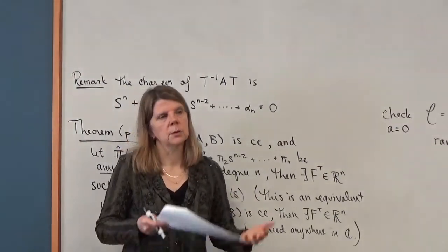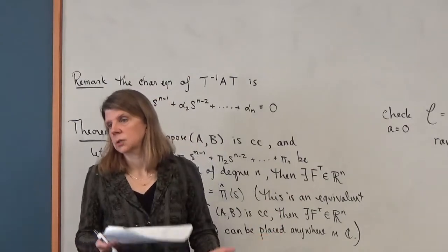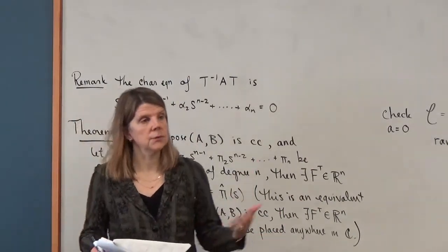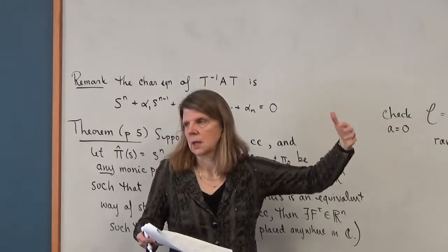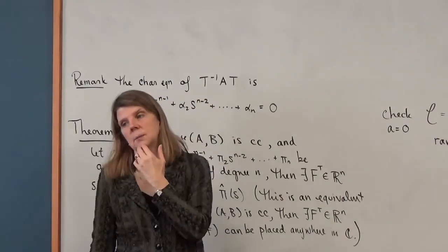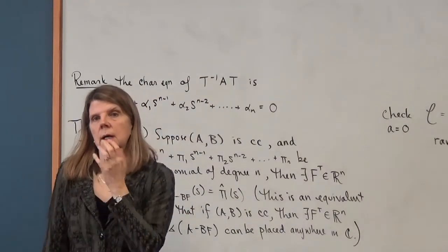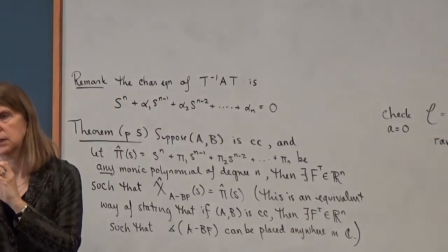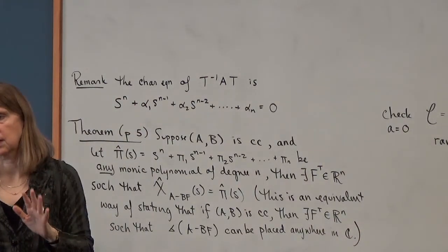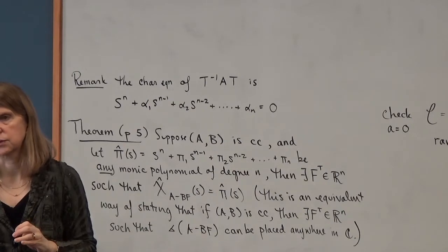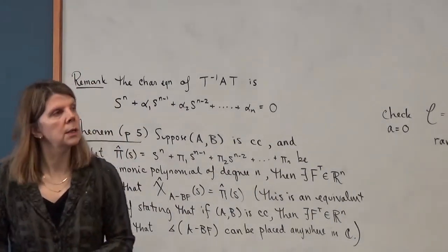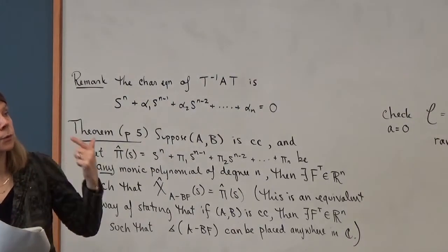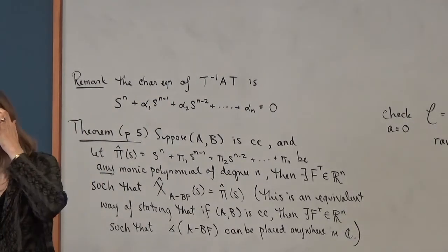Large control input, perhaps amplification of any noise that you might have. So sensor noise, I mean, we're measuring state here, but measuring that state, that noise gets amplified by F. So typically you try to do the least amount that you need to do to get the system to do what you want it to do, so that you don't have large gains in your feedback loop. We'll come back to that point, as we'll revisit it when we talk about observer design as well.